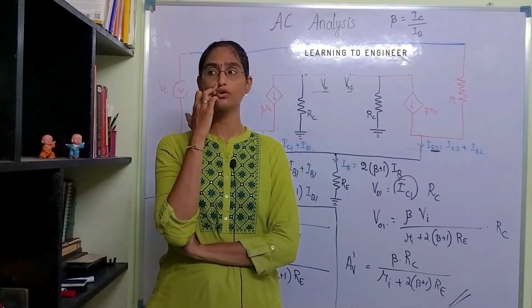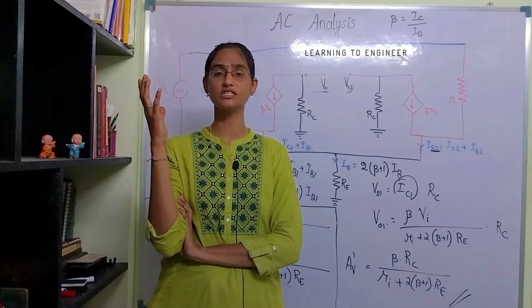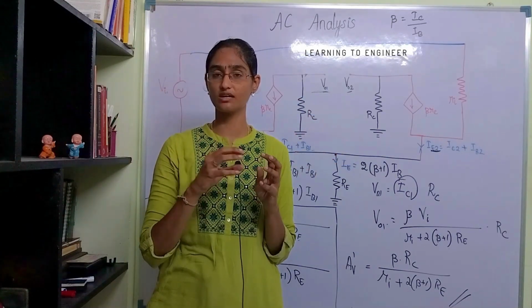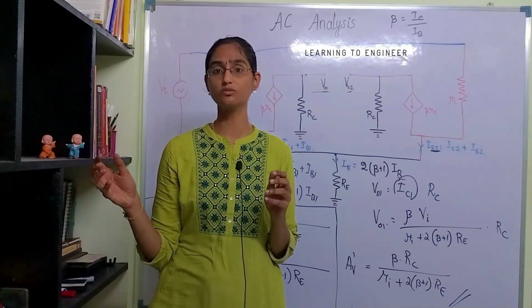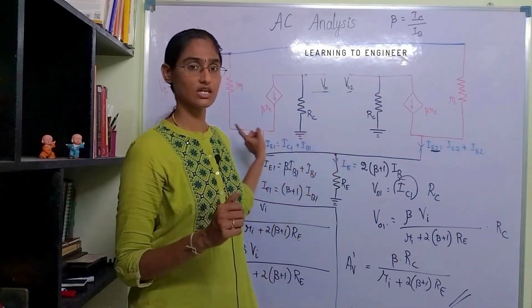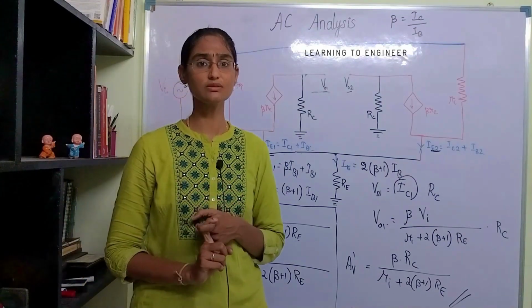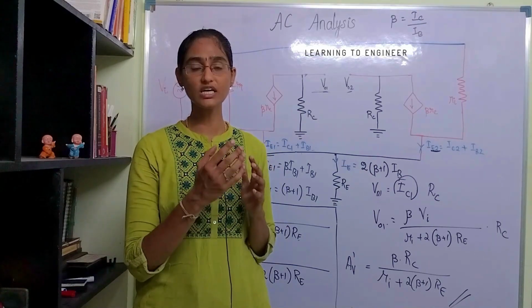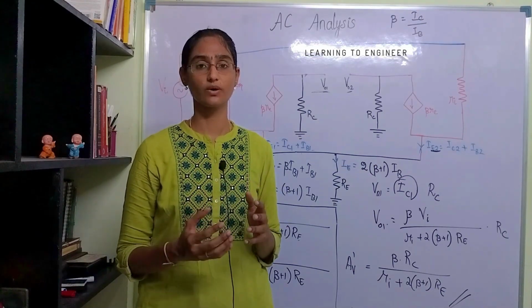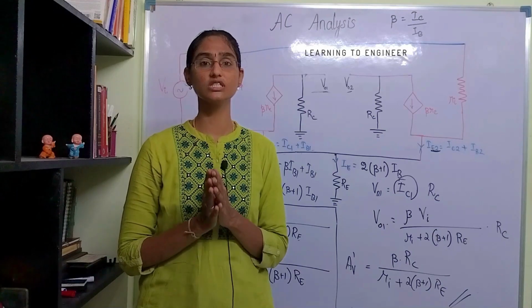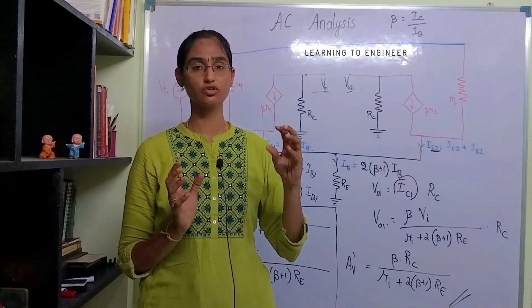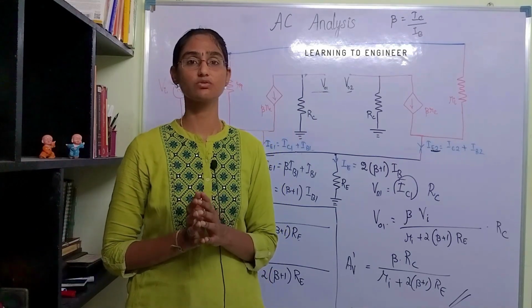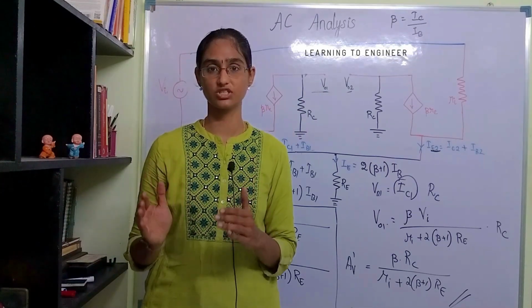Say for example, you are applying the same AC signal to the inverting and non-inverting inputs. Ideally, the output from the output pin is supposed to be 0 because we are applying the same signals. But practically speaking, this will not be 0. This is due to the operating DC supply that's present. So the common mode rejection ratio defines the ratio of differential gain to that of common mode gain. That is what CMRR, or common mode rejection ratio, is.